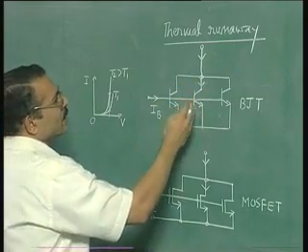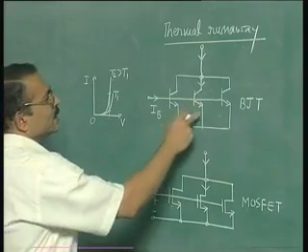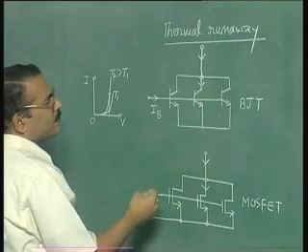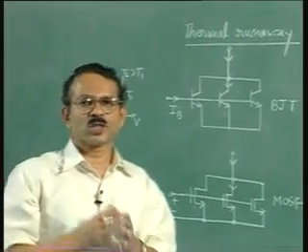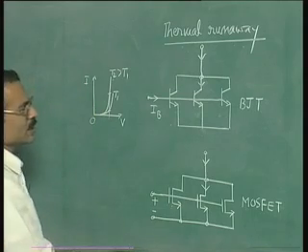This is like a thermal runaway, right? It is a situation going out of control, and this device will end up hogging all the current and in the process heated up, and it may also get destroyed. Whereas in the case of MOSFET, no such thing happens.